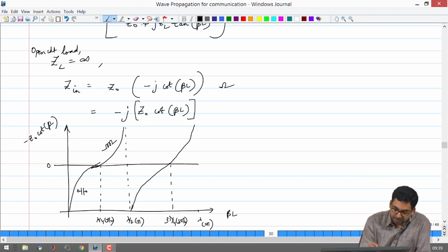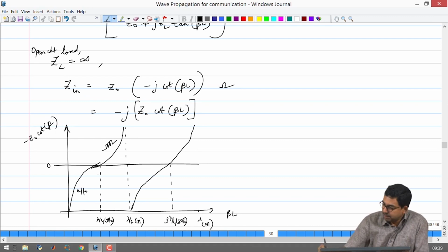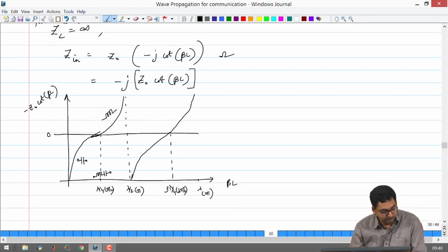In the zero crossing, it means that the impedance is 0 or it is a short circuit, that is your current is going to peak. Okay. In those cases, the equivalent circuit where the current is going to peak is going to be a series combination of L and C. If you have series combination of L and C, and if your inductive reactance matches the capacitive reactance, alright, then you will end up having a short circuit and your peak voltage is going to be just source voltage divided by source resistance, okay, that is going to be your peak. So, the equivalent circuit at the place of zero crossings is going to be L in series with C.